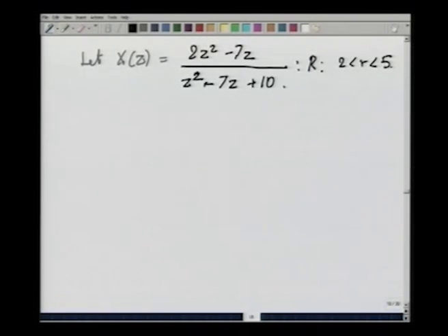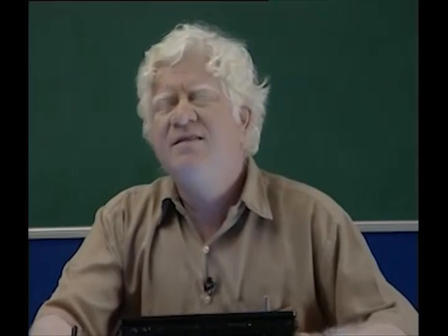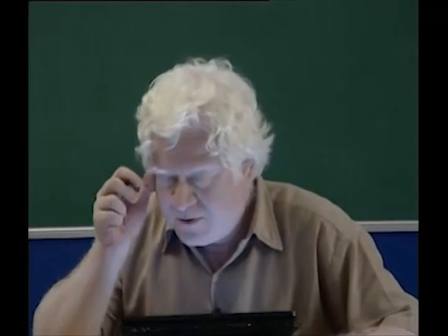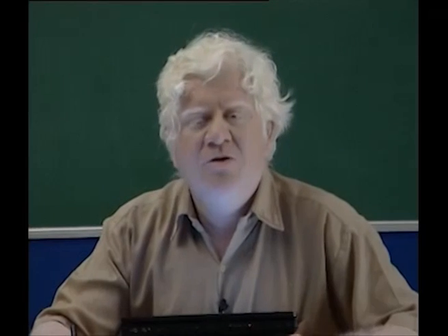Now, from our knowledge of the properties of the Z transform ROC that we have just acquired, this seems to suggest right on the face of it that we have a two-sided signal, because the ROC is annular. The first task is to do a partial fractions expansion.